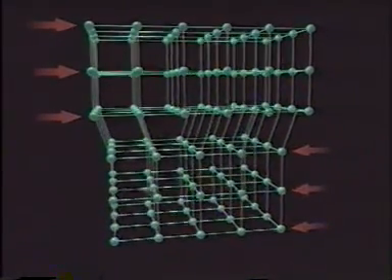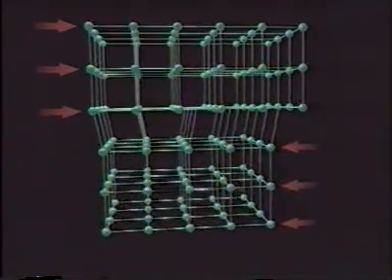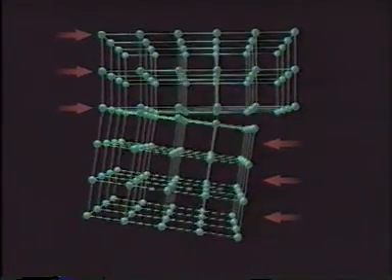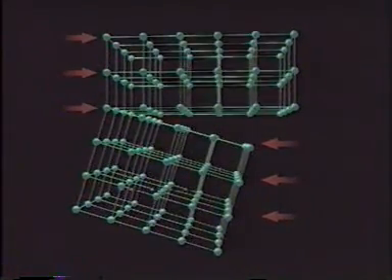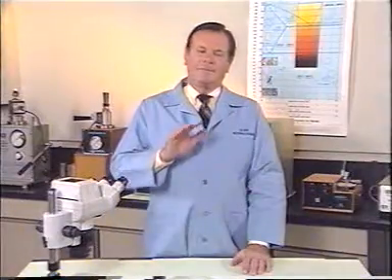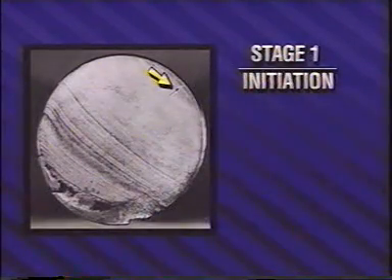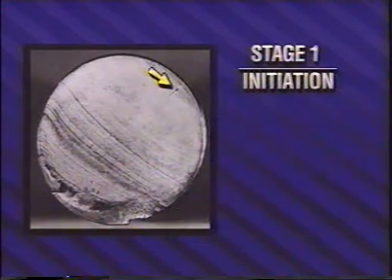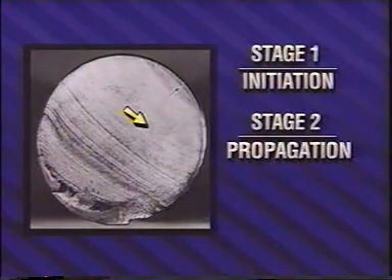They result from the repetitive shear stressing of the crystals at levels well below the tensile strength of the metal and even below the yield strength of the metal. This initiation stage of fatigue is difficult to envision and even difficult to describe. But these unseen, gradual, submicroscopic crystalline changes do exist and do tend to accumulate. Eventually, tiny cracks form at one or more locations, and the failure enters the second stage, propagation.